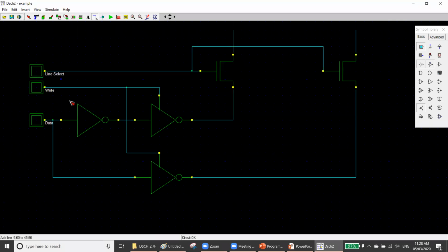Now see what I just made here. This is a row selection decoder. No, not row actually. This is a column decoder. Here you have two NOT gates. One, another one. So your data will be, if this is 1, this will become 0. This will become 1 again, right? So your 1 remains as 1, and for this one here, this is your 1, so 1 will become 0. So this is your data line, this is the data bar line. So when it is 1, this is also 1. When it is 1, this is 0. That means the data bar line, right?